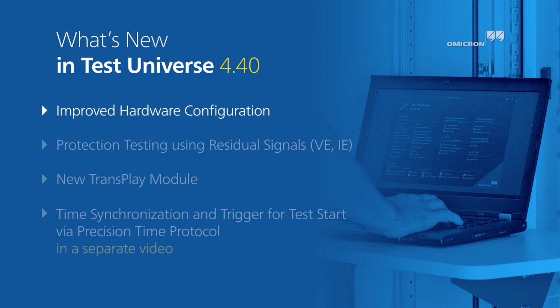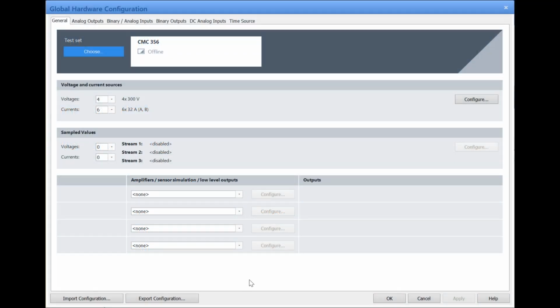So let's start with the hardware configuration. Once you've opened the hardware configuration of a test plan, you see that it looks slightly different. At the top, you see the test set type currently used and its status. To go online with the device or to change the type, you would use the Choose button here. Below, for the voltage and current sources, we have changed from number of systems to number of signals. That means here you would just select the number of voltages and currents you would like to use for testing.